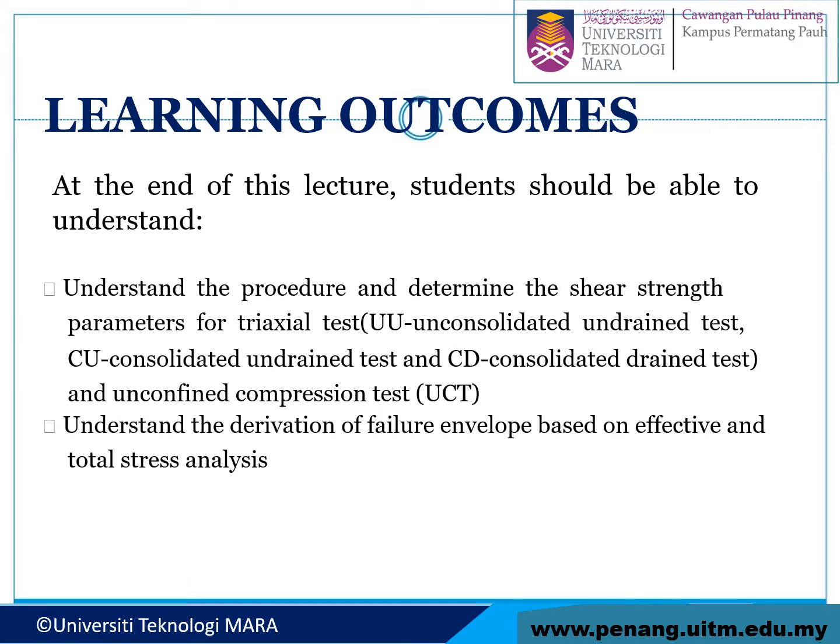Learning outcomes. At the end of this lecture, students should be able to understand the procedure and determine the shear strength parameters for triaxial test using UU, unconsolidated undrained test, CU, consolidated undrained test, CD, consolidated drained test, and last one, unconfined compression test, which is UCT.